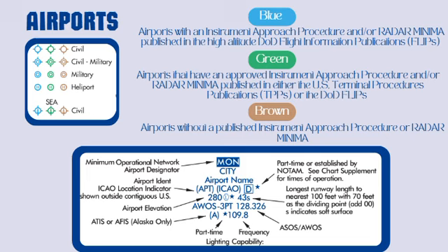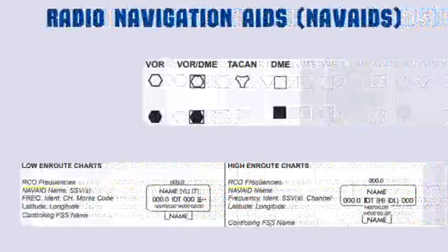Also, they have some services that may include additional notes about availability of fuel or other services marked by symbols or annotations, and instrument approach types. Airports with a specific instrument approach, such as ILS, RNAV, or VOR approaches, are included, making them more reliable for IFR operations.